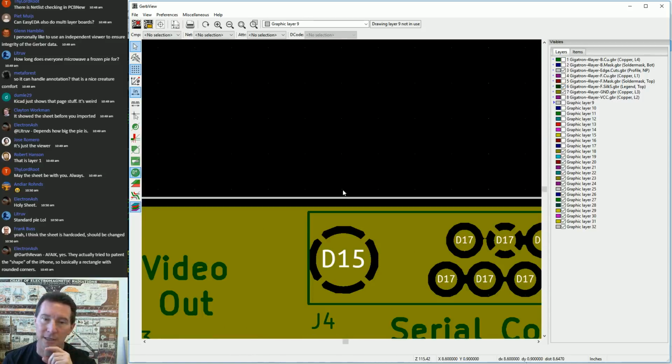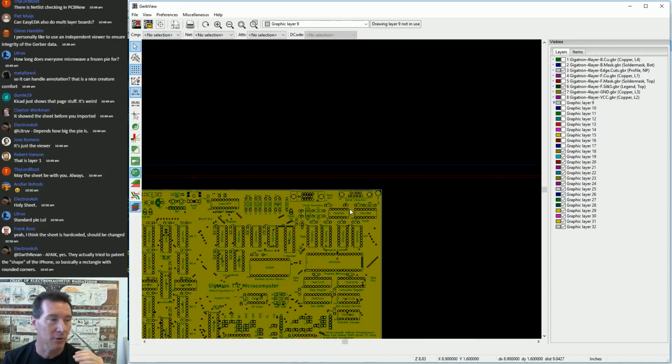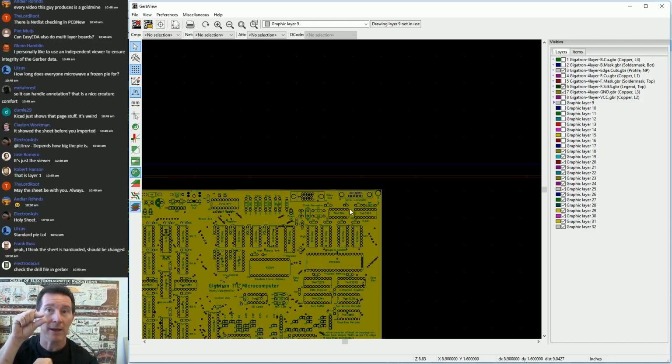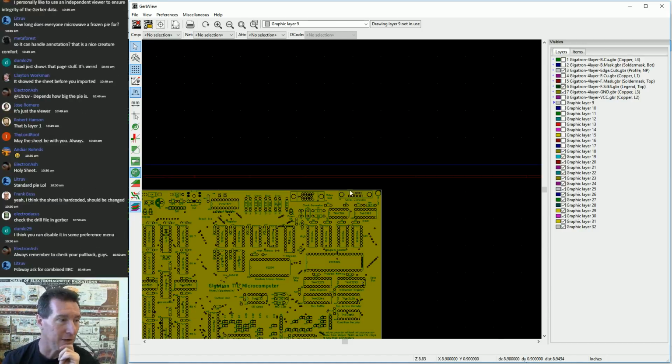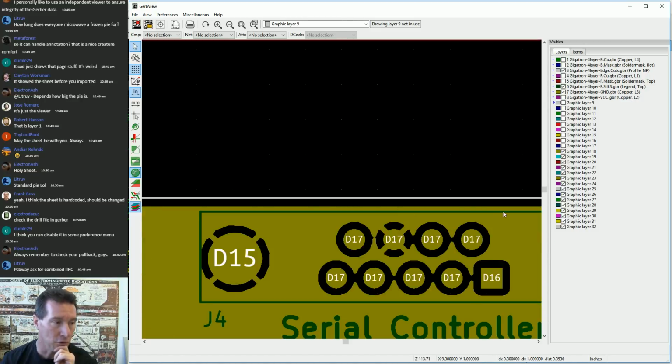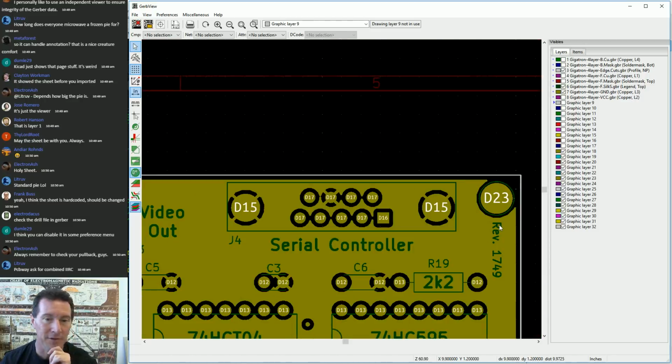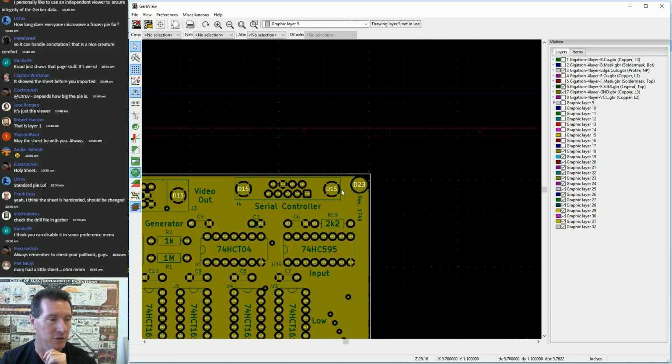Like I said, here's the important stuff. You do not want this copper to go right to the edge, especially on a multi-layer board, where the inner planes are usually on a very thin pre-preg. When you saw the edge of the board off, or route it off, you can get burrs and you can easily short out your copper planes. Huge trap. Many people have come a gutser on that one. So you do not want that copper to go to the edge of the board.